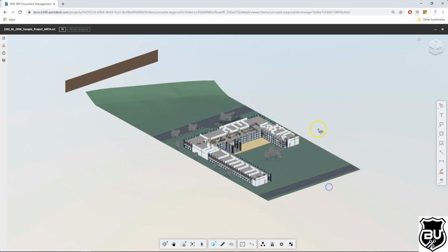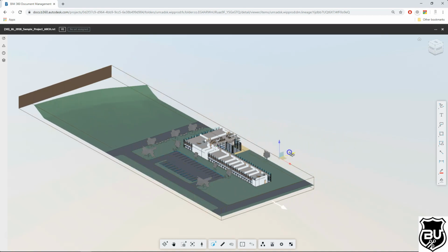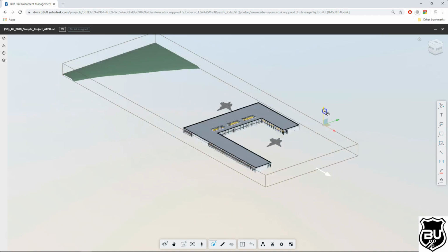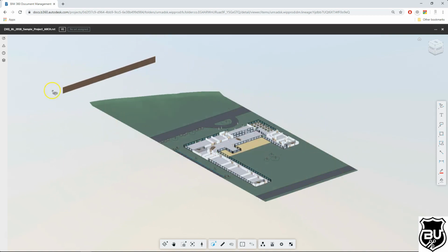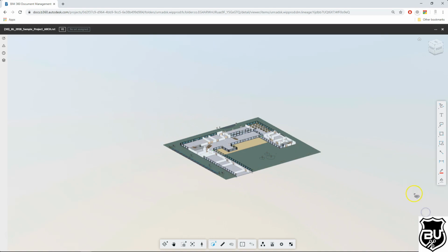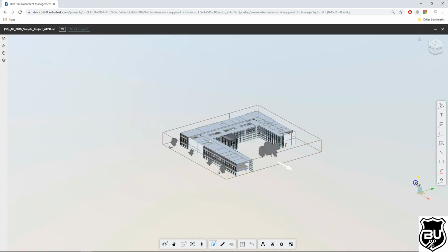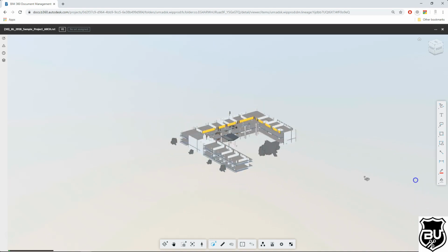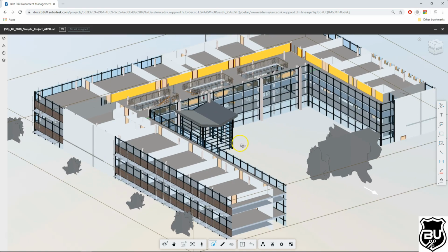The ones in blue, green and red, when you hover over them, if they're active, they'll be yellow. So you can click and drag on them. It might take you some time to play with these settings here. Then you can actually see the interior of your building using this tool called the section box.